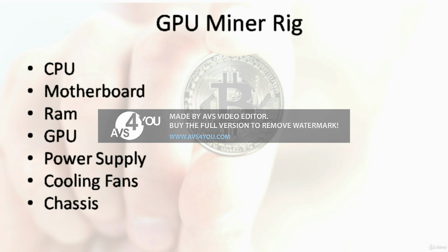Other things to keep in mind when sourcing the GPU is that it should have more than 3 gigs of RAM, an open air design, and you should also keep all the same GPUs within the rig, so that all of the GPUs within this particular rig should have the same model and the same type. So basically, I would recommend you to purchase all of the same GPUs at once. Another thing that I would like to recommend is to get GPUs with a back plate, as not only it provides extra protection, but also has better heat dissipation as well.